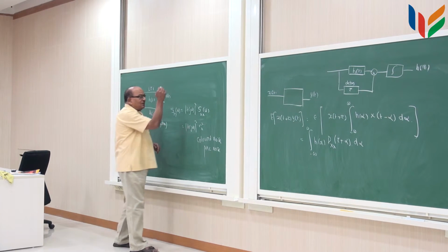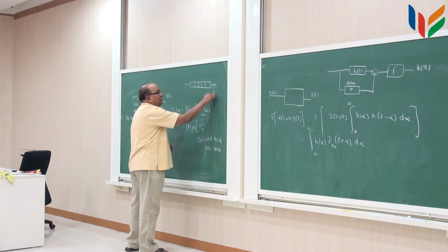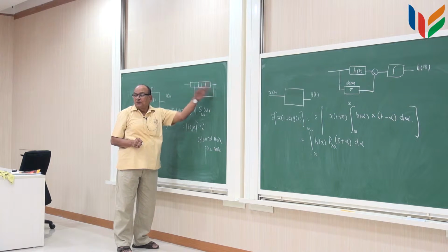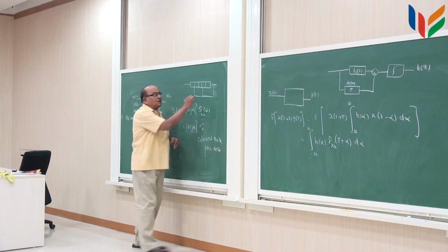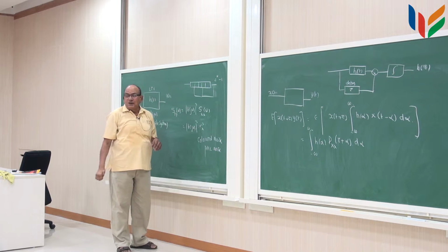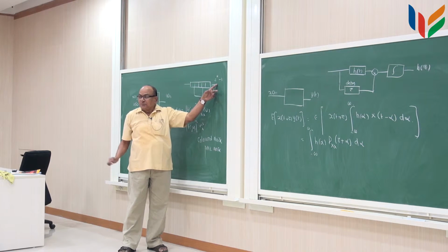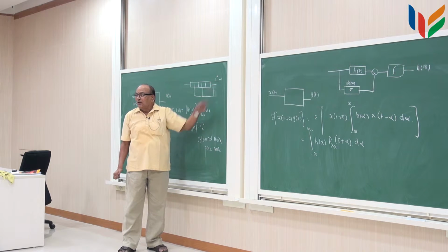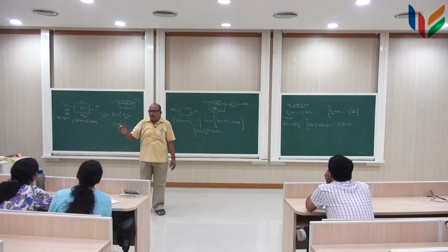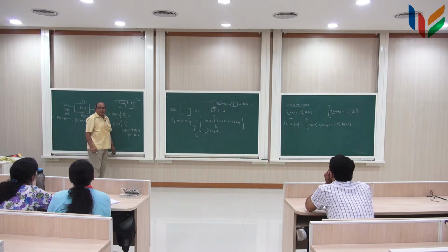Remember in 102 we said that if you have a shift register and then take the output and feed it back, this output here is a periodic sequence, and this periodic sequence length is equal to 2 to the power of n minus 1, where n is the number of stages of the shift register. Depending upon what feedback connection you have here, you get a binary periodic signal of length 2 to the power of n minus 1, which is either 1 or 0, but the changes from 1 to 0 will look random. Not random, deterministic, but almost resembling a random variation.